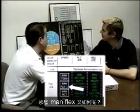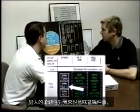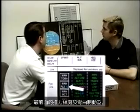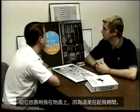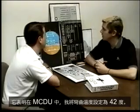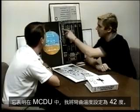What about MAN FLEX? MAN FLEX indicates a couple things to me. First of all, it indicates that the auto thrust is armed, that the most forward thrust lever is in the flex detent, but it also indicates I'm on the ground because this is during takeoff, and it indicates that in the MCDU I've set a flex temperature of 42 degrees.